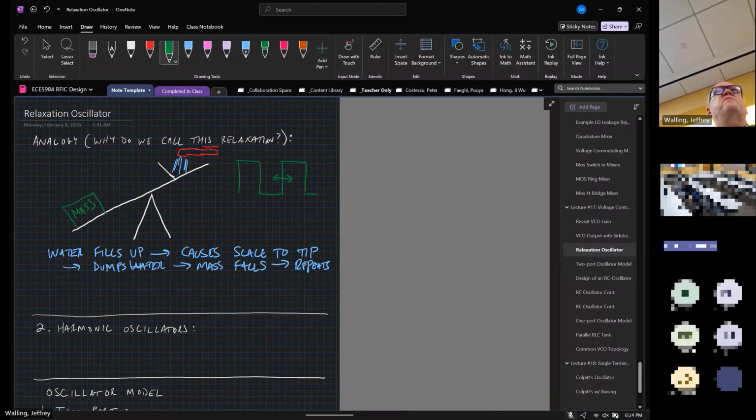Now we expect when we have a clock signal that the clock always arrives at some predefined period. So 500 nanoseconds or something like that, the edge of the clock will always be at 500 nanoseconds. But due to random fluctuations in the performance of our devices, the connection to the supply, all kinds of things, the edge of the clock is uncertain, and that's called phase noise.